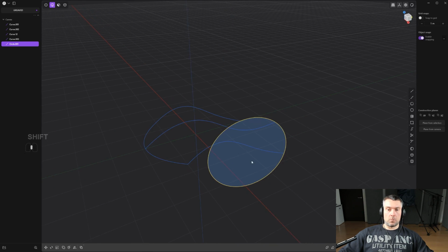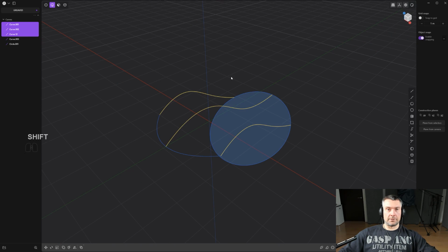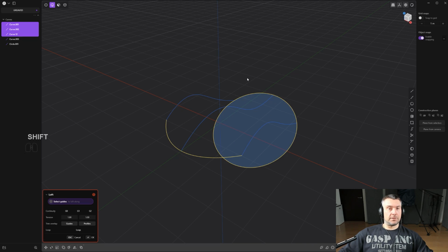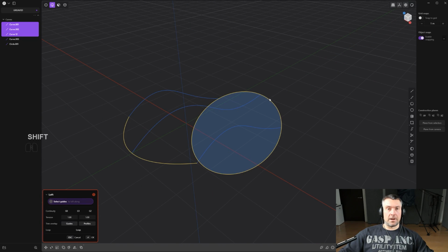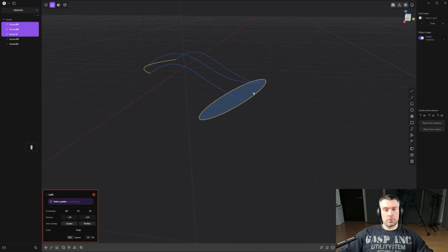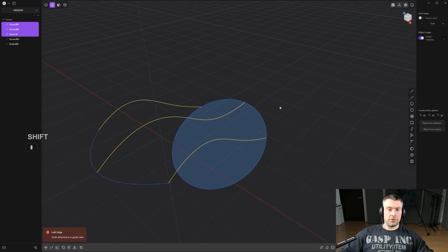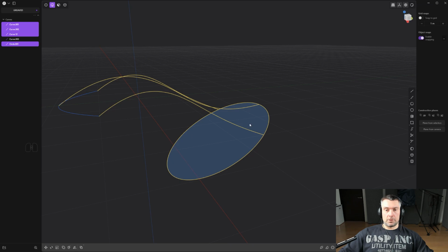Okay? So now watch. If I want to loft this, right? So I'm going to select all these, which defines the curves across which I want to create a surface. Press L. And now you can hold Shift and define the profile of this loft. Now this didn't work for a reason. It's basically selecting this entire area and lofting gets confused. So what you want to do is trim it. Now in order to trim something, you need to make sure that all these edges are actually connected, all right? So in our case they are.